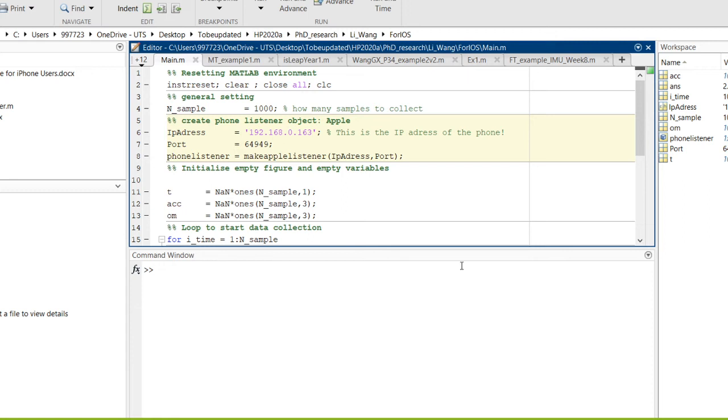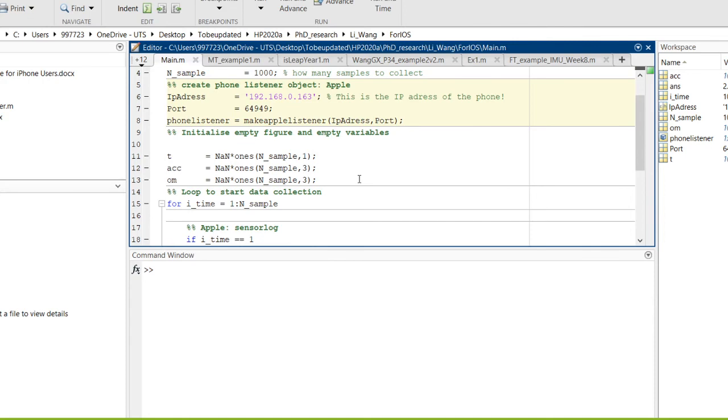Of course, you can increase the sampling frequency, but the maximum sampling frequency is 100 hertz. That means you can only measure up to 50 hertz of body movement. If you set it to 20 hertz, you can only measure up to 10 hertz of body movement. In that case, maybe we do not need to design a filter, because we have already gotten rid of the high frequency noise. That is the good thing. Maybe I will introduce how to design the filter, but you may not need it for your project. So the second stage is filtering, if necessary.